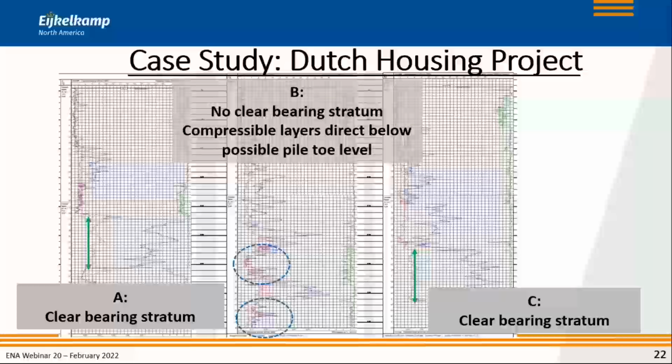One more question that I think I have time for: is pile driving simulation a replacement for a test pile? Pile driving simulation, in my mind, can very well be a replacement for a test pile. If you have a good soil investigation and on that basis design your pile and derive your bearing capacity, and you then show that during the pile driving installation the predicted results very closely match the actual results, you may not need a test pile anymore.